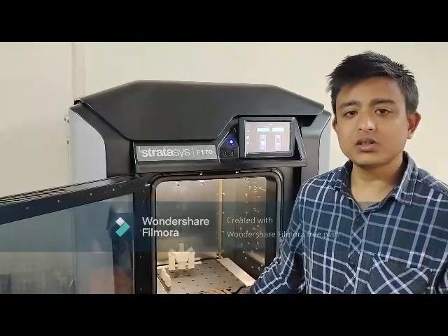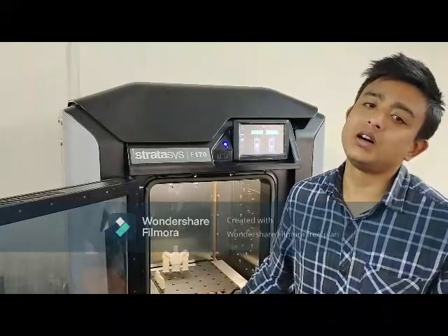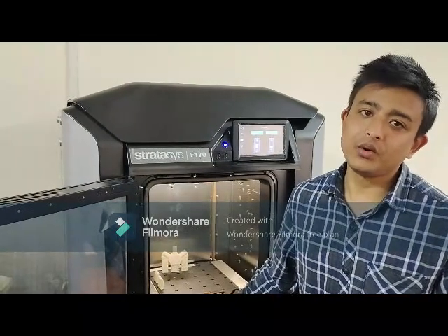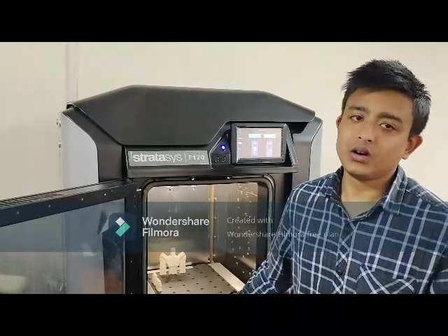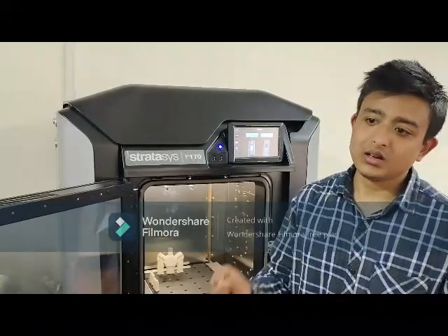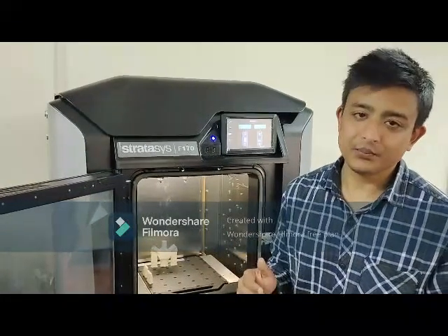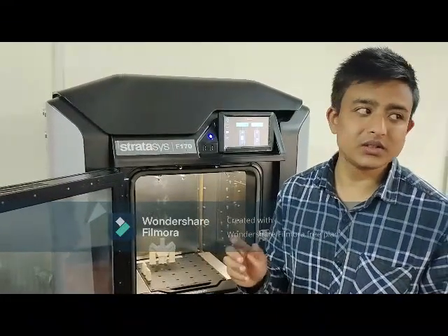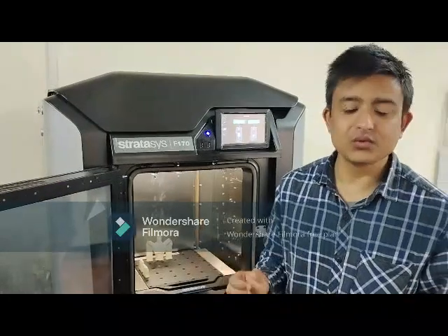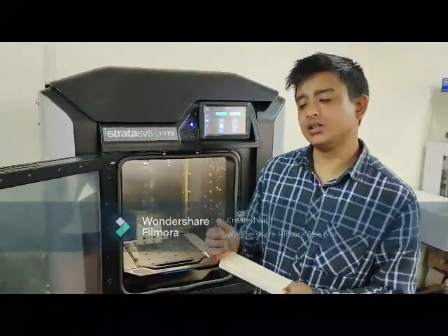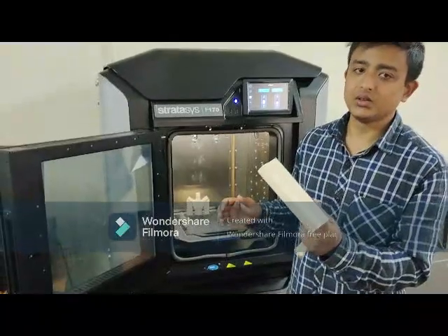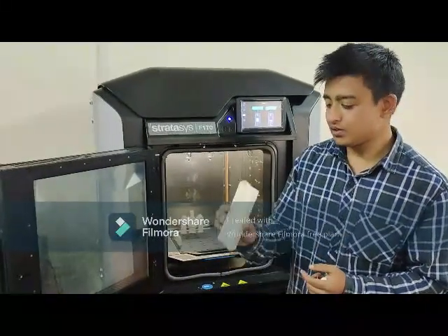Secondly, suppose the printer is overheating the nozzle, then what will happen? We will have excess amount of flow rate, and the diameter of the filament will be very less. It will be more like liquid. It will not be viscous. It will be more like a non-viscous fluid. So to check all these things, a purge tower is built. Fine. So this is the use of purge tower.